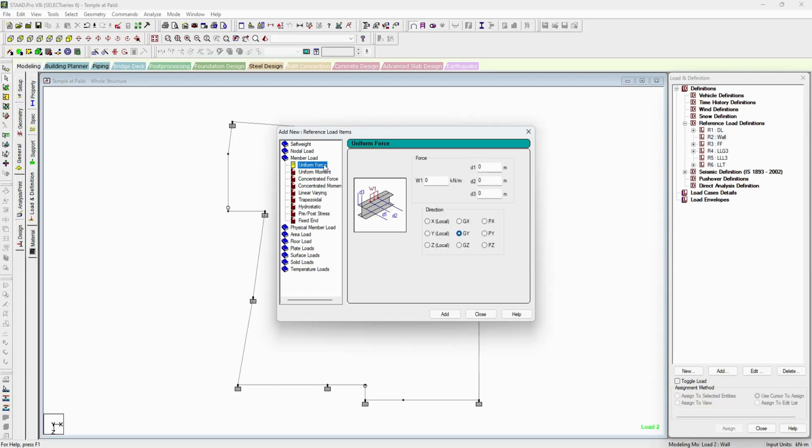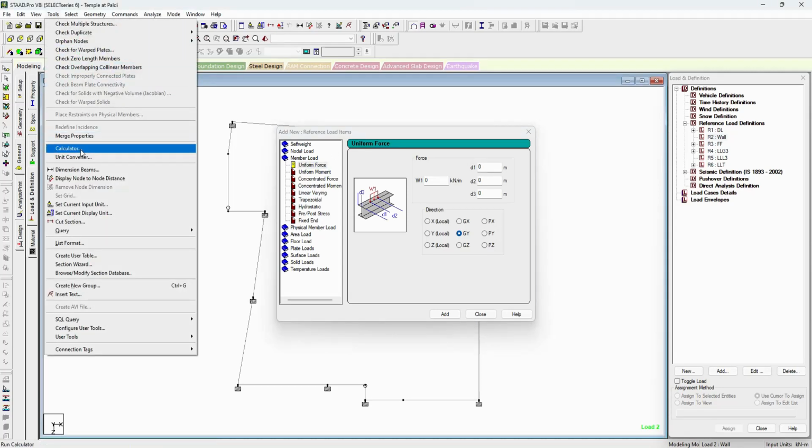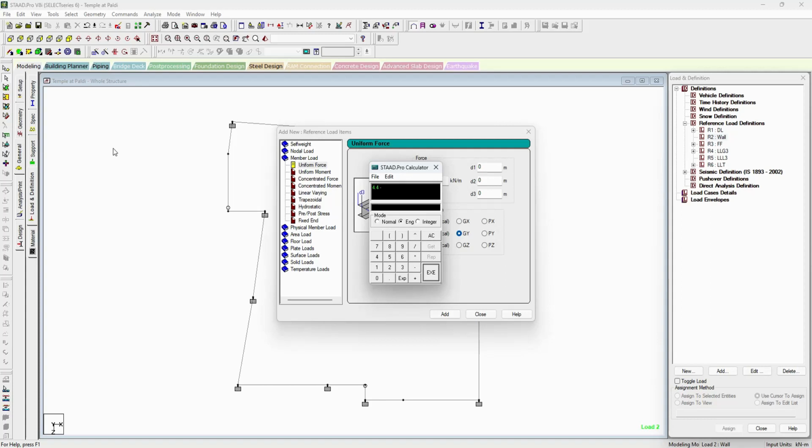As the total height is 4.4 meter and your top beam shall be 450, the wall height shall be 4.4 minus 0.45, that is 3.95. Let us say 0.23 plus plaster of 0.012 at the outer edge and 0.006 at the inner edge will give you 248 mm total thickness of the wall. Let us say 0.25, that is 250 mm thick.